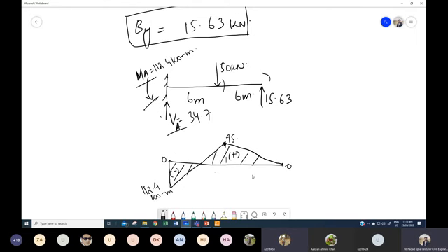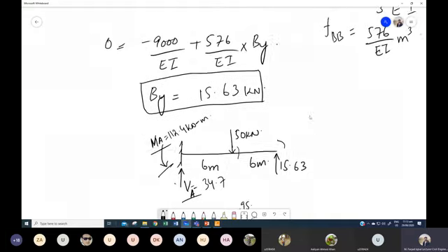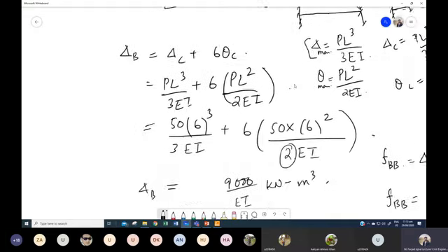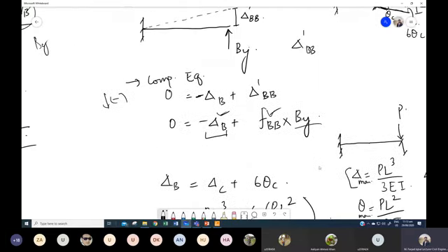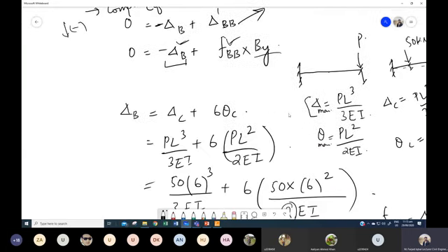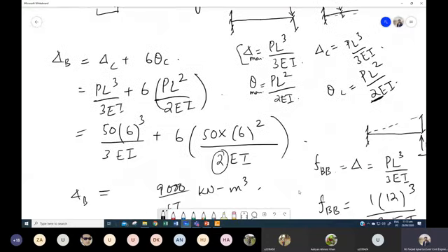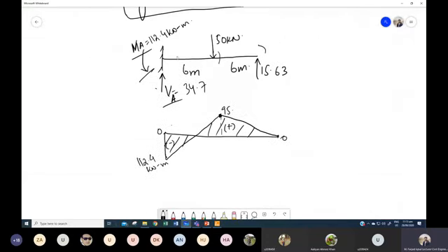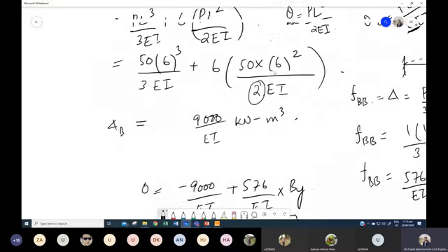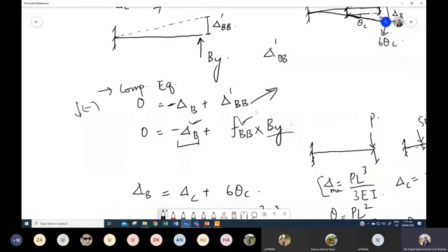This is your bending moment diagram. Now if you see this question, what is the only difference here? We did one new thing, that is this compatibility equation. Apart from that, we have studied everything earlier: this deflection method, this bending moment diagram, and calculation of these unknown forces. So if you can write this compatibility equation correctly, then these questions are not difficult. It is same like the equilibrium equation.